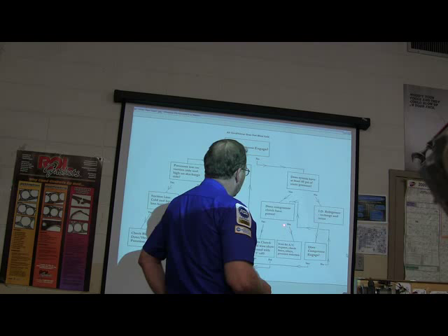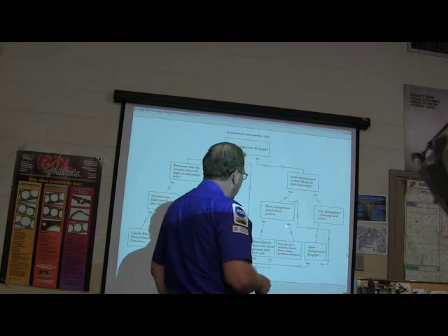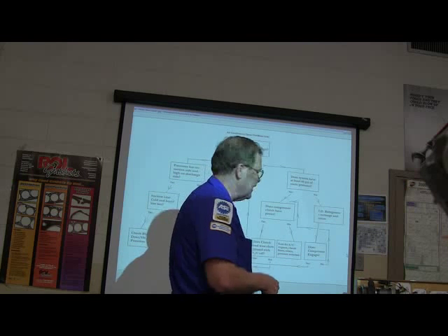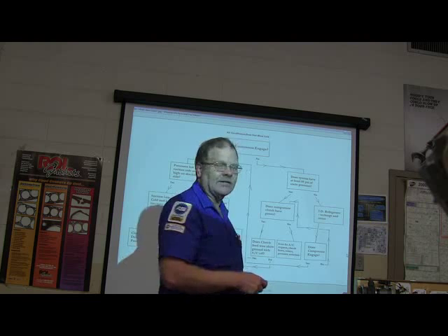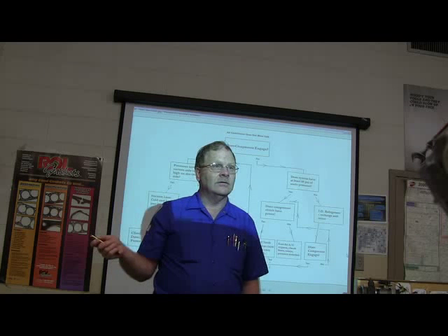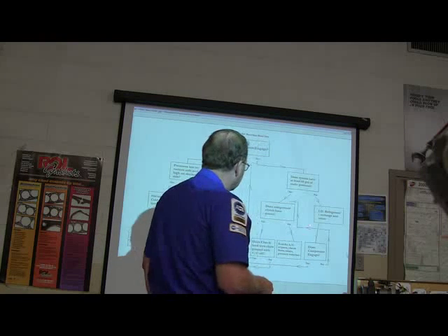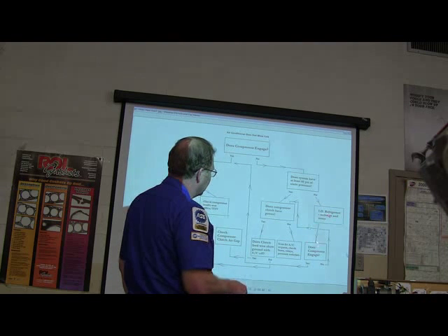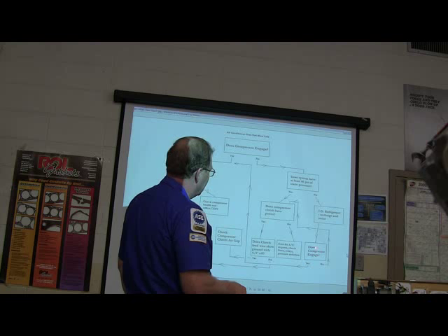Okay. Does the compressor clutch have power? No. Scan, check for AC request, check fuses, relays, pressure switches, and so on. See, this is a generic sort of a thing here, and a copy of it's available. You might notice it's right here, too. I printed it. All right, so right here, after you add your refrigerant recharge, does the compressor engage? If you say no, then you go back up here, does it have power? See, that kind of goes in a loop there.